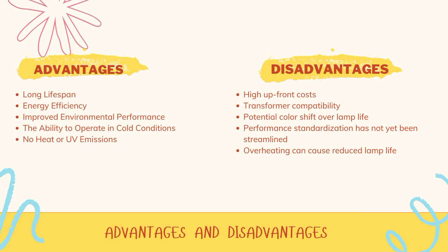For the second part, disadvantages. Firstly is high upfront cost. Secondly is transformer compatibility. Thirdly is potential color shift over lamp life. Fourth is performance standardization has not yet been streamlined. And lastly, overheating can cause reduced lamp life.